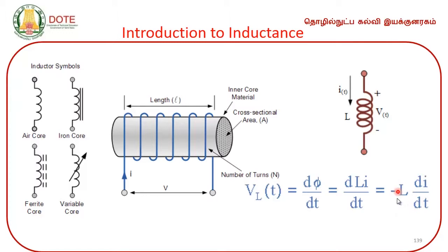See here you get minus. Why? di by dt, rate of change of current? Because when current changes with respect to time, both in magnitude as well as direction, here you get the dynamic flux around the coil. So it induces the voltage which opposes the cause voltage. The induced voltage generated here opposes the supply voltage. That is why we put here negative sign, minus.